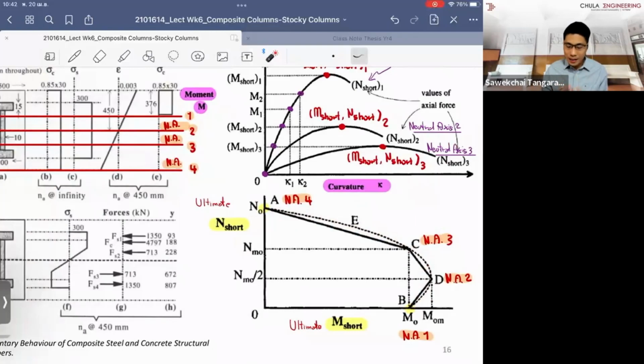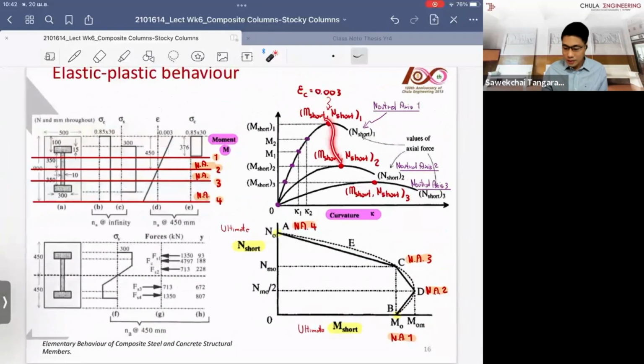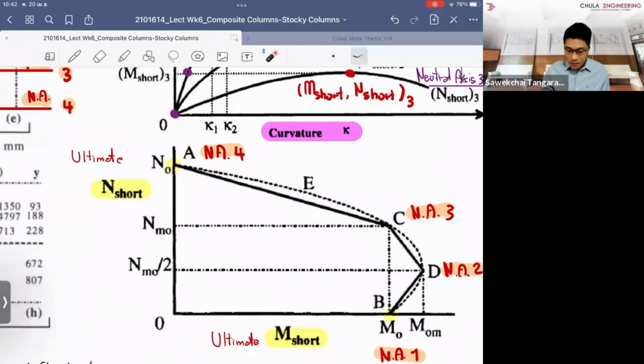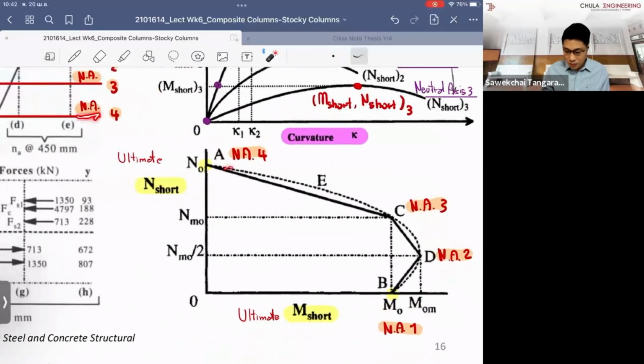It collects the information on the capacity of the beam or column, which combines the axial force and the flexural force, and this is the curve you have here. If you keep varying the level of the neutral axis depth finely enough, you may start from the bottom, keep increasing slightly, and you will have a smooth curve, as a dotted one.